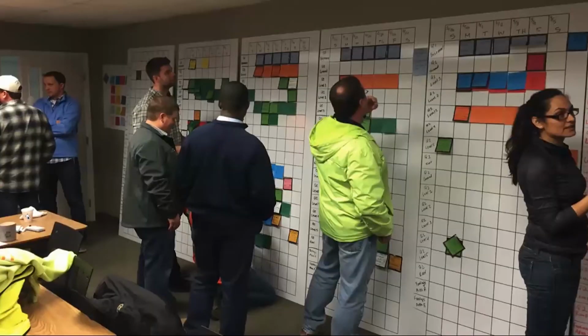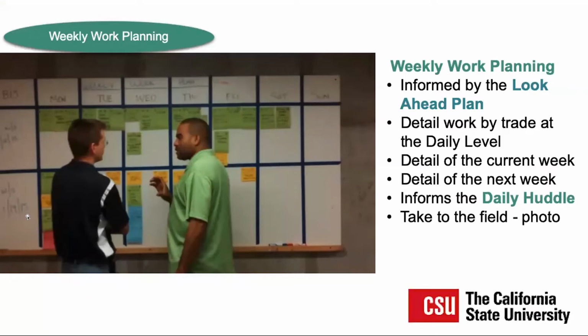This is a project for the Veterans Administration up in Seattle. But you can see here they also have boards. They have swim lanes, which are really by geography and zone within each of the floor plates. You can also see the way they stack the trades: the color of the tags is tied to each of the trades. Color is specific to a trade. Typically you only have one trade in an area at a time, which allows them to get very productive. What they've done is make the area available to the trade smaller in order to try and speed up the overall production of the job.